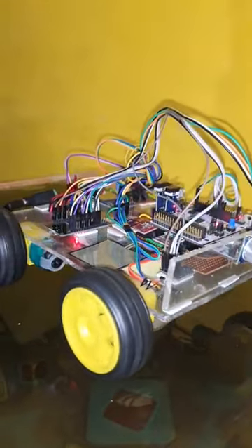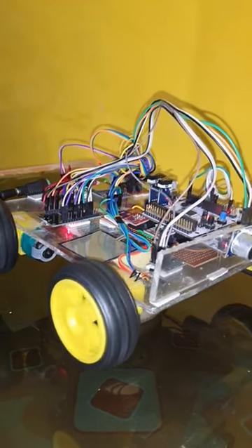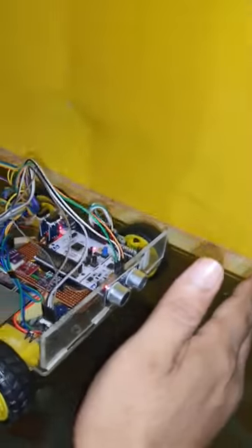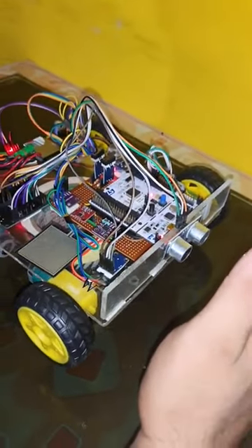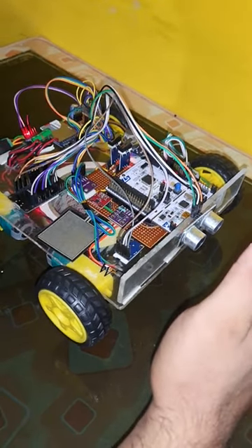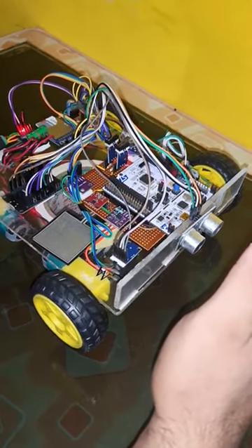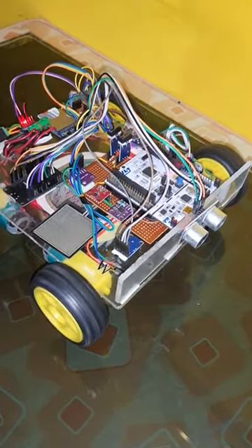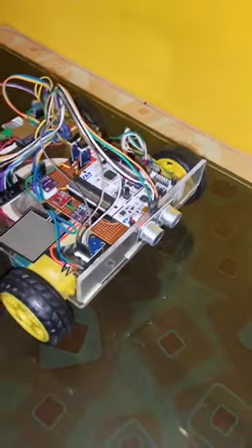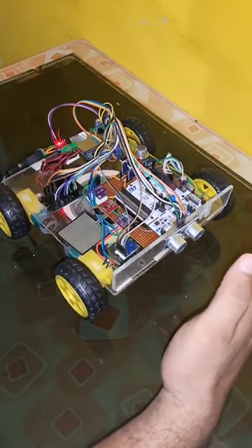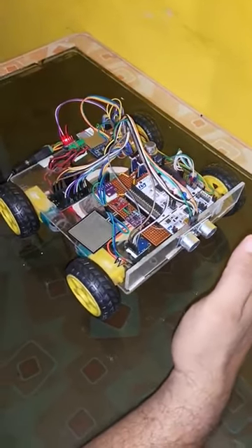We can see the emergency brake first with the ultrasonic sensor. If I put an obstacle here, the car stops immediately. And if the distance is between 10 and 30 centimeters, then the car will apply a slow brake or reduce its speed. We can see here, this is the regular mode, and now I will put in the obstacle. We can see the car reduces its speed immediately as it comes near the sensor. Yes, the car stops. So two conditions are proved.